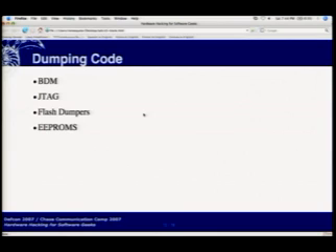It uses some proprietary burst protocol, which is not at all a standard. So for different devices, you have different BDM pinouts. Some of them will be 8 pins, some of them are 6, and all of them require different pods, and it's a very expensive way to do development. But each pod's only about $50 to $100, and if you notice the Freescale pods, if you connect them backwards, it'll short the pod and you need a new one. Yeah. So you can go through a lot of them if you're using those in your manufacturing process.